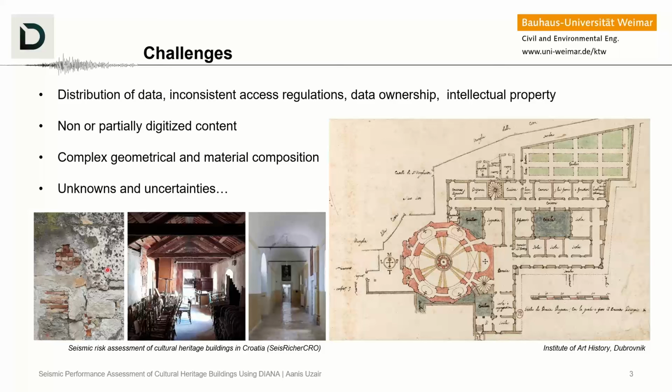So when a wall is made from such a complex combination of different types of material laid together, then forming a continuum model out of this becomes a very complex case that we typically deal with. So characterizing such type of masonry where data is very unavailable or where you cannot make material tests because of the cultural integrity of the buildings, it becomes very complex to model the nonlinear material response in a realistic or in a certain manner.